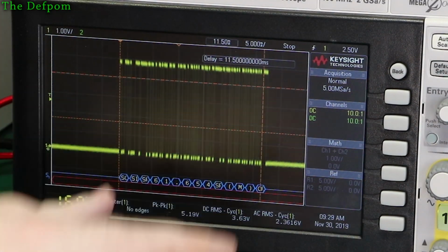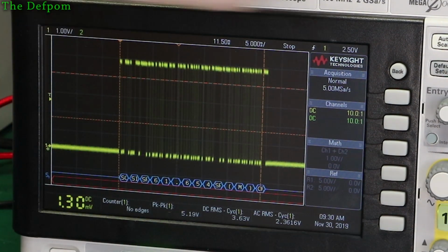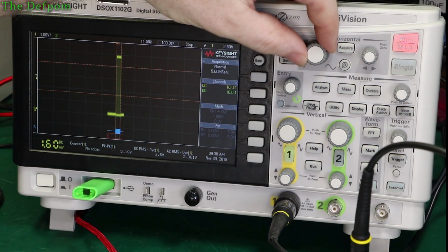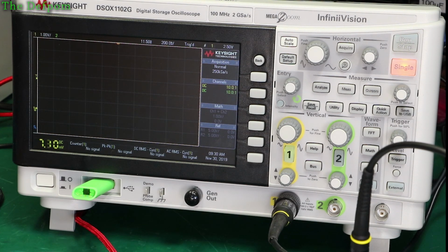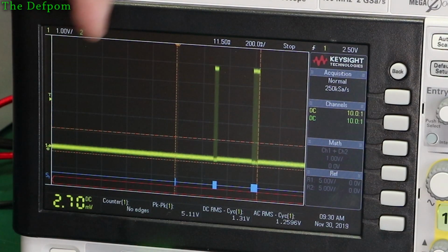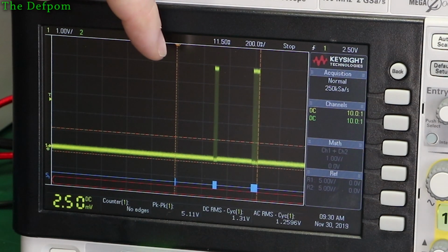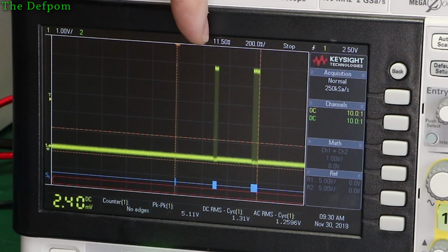So I'm having to decode this. As you can see, it's idle low state at that point from the device. If I bring this down some more, do another single capture, and now I'll do a start really quickly. There we go. You can see that's a start point. That's when I've started the timer. That's when I stop the timer.